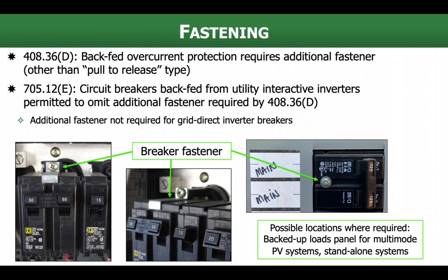And so that's going to require that fastener, and standalone systems as well, where we don't have a primary power source, or the standalone system is the primary power source. So it needs to be fastened into place because, once again, it's creating the voltage waveform. I pull that breaker off the bus bar that's being backfed. The breaker is still energized.